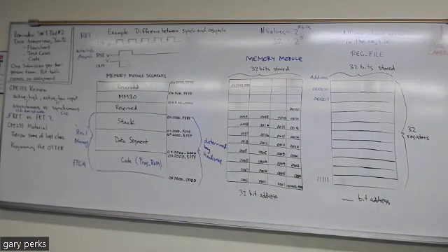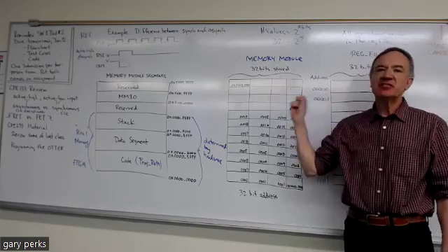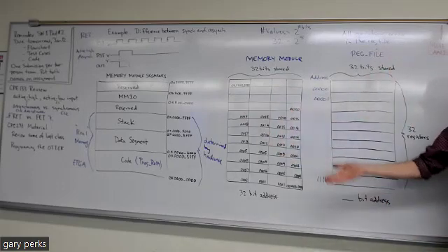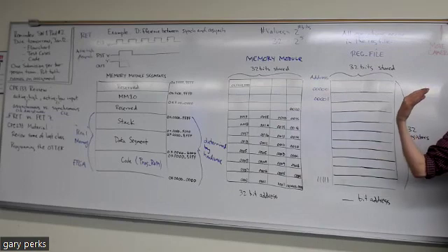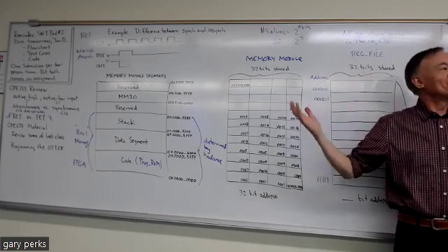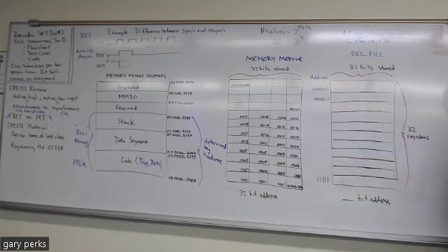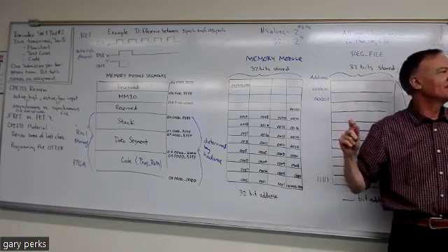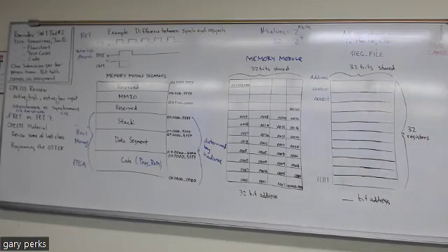All right. The next thing I want to talk about gets to why the memory module is byte addressable. You might be wondering, why is the memory module byte addressable and the reg file isn't? Well, the quick answer is because of how we use them. Because of how we use the reg file, we don't need it to be byte addressable, but because of how we use the memory module, we do need it to be. What it has to do with is some of the instructions in our instruction set.